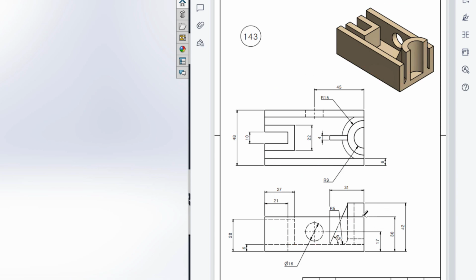In the front view, I will draw a rectangle, and this rectangle has a dimension of 45 multiplied by 2, which will be 90 unit in this here, and we can see it has a vertical distance of 30 unit. Then I will extrude boss it to 48 unit.